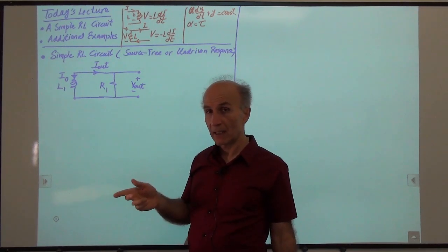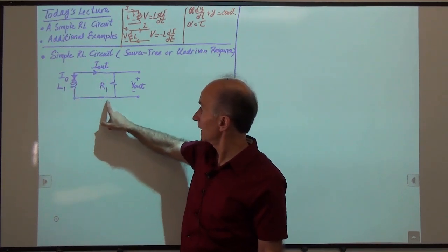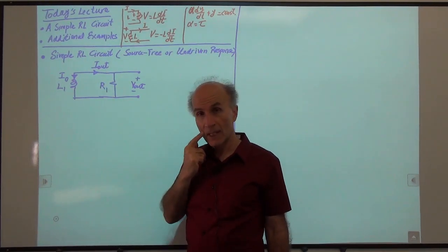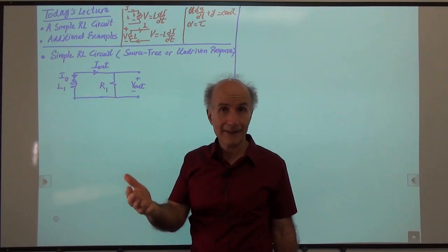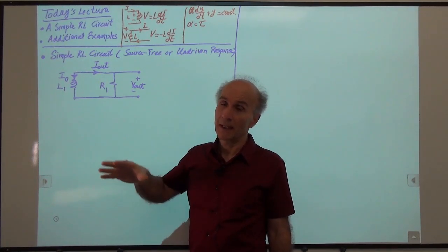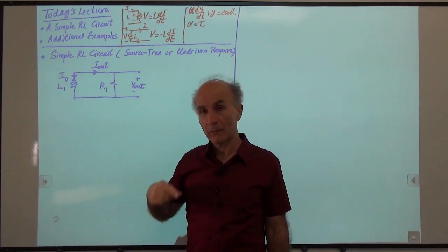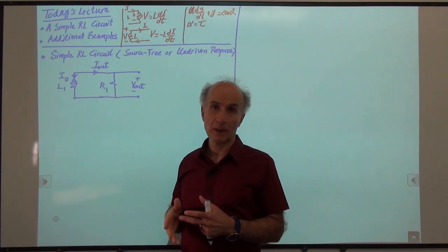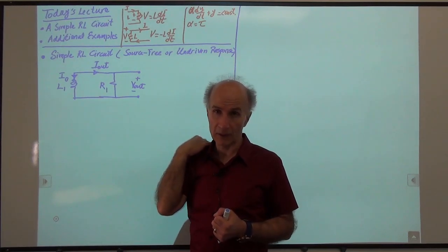All right, but then that current through the inductor also flows through this resistor, right? You can see that it has nowhere else to go. It comes down, it goes this way, it goes up. As that current flows through the resistor, it creates thermal loss in the resistor, right? It creates heat. The resistor heats up. So the energy is lost from the system in the form of heat. It goes away. So as time goes by, whatever the transient might be, the current through the resistor is extracting energy from the system and dissipating it in the form of heat.